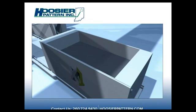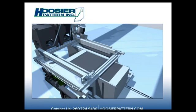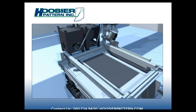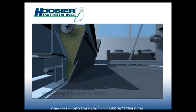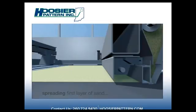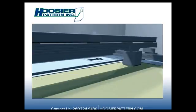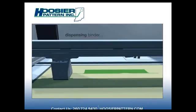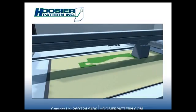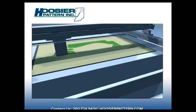And right now you can see there's a job box going in. You can see where it filled into the recoater, and here in a second I'll show you actually laying the layers. Every time it prints a layer, that box drops 10 to 11 thousandths. It'll lay a base layer, and then the print head goes back and forth. It's kind of like printing a book report. You need a whole sheet of paper to print out one picture or one paragraph. Same thing with any of the sand printers. You still need that full layer.